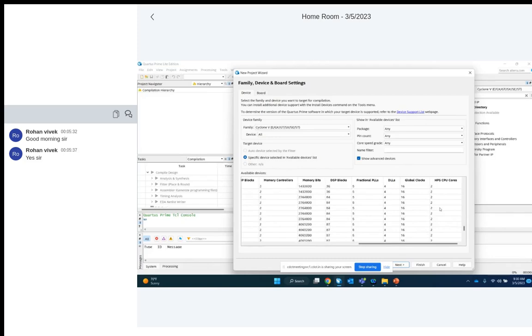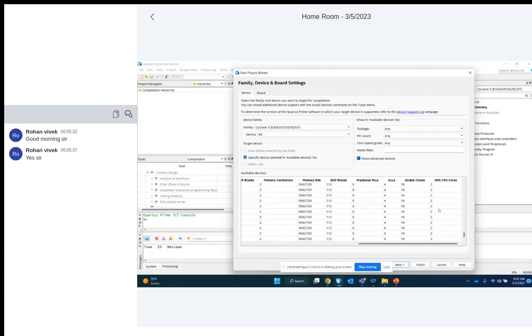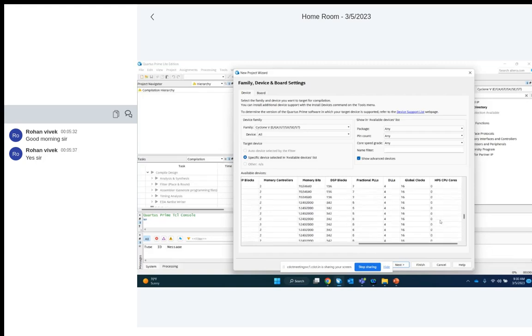So what is very important for us is before we start generating the system, we need to select the device correctly. That's what we are trying to do here. When we try to find the device correctly, we need to ensure which family we are doing. How do we know? When you say this SX family, which starts with S means SOC. SX, SE, ST, all these are SOC families. When it is GX or GT, they are the devices with the transceivers, okay, which is only FPGA.